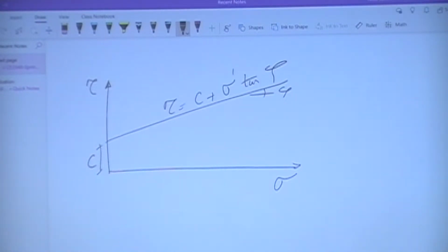And then we talked about crushed material versus rounded material that you can source from the riverbed, right? So for instance, if we have crushed aggregates that are coming from El Paso quarry, they have better interactions in terms of the frictional properties compared to siliceous river gravel from Rio Grande. Yes, they do have that, right? So that's another way to think about the contribution of the phi value to the strength of the material.